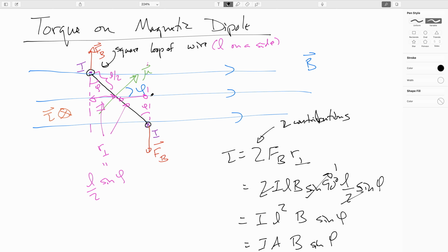So the trick with a motor is right at the split second that the magnetic moment aligns with the magnetic field, you flip the direction of the current going through the windings. This is usually done using a device called a commutator, if it's a DC motor. And so when you flip the direction of the magnetic moment, now once again, you're going to be exerting a magnetic torque to try to align it. And then again, you rig it up so that at the instant it's aligned, you flip the direction of the current, which flips the magnetic moment. And so it keeps endlessly applying a torque on the loop to make it turn around. And that way we can do useful work and make cars go down roads and stuff like that.